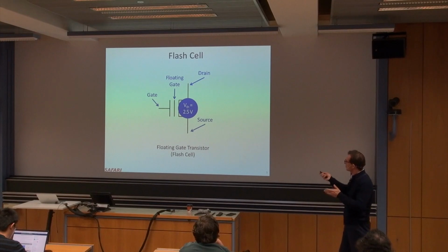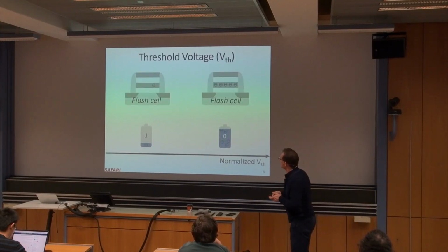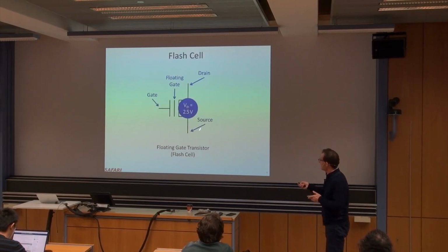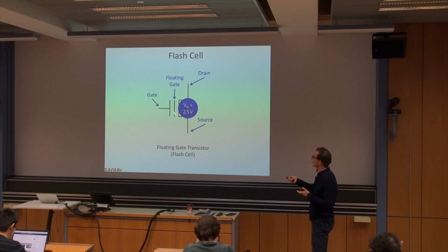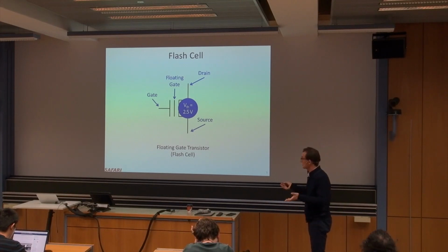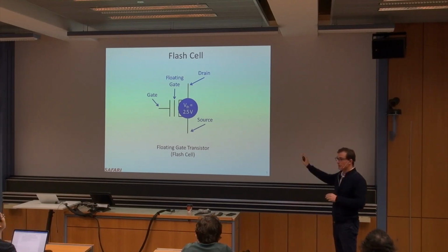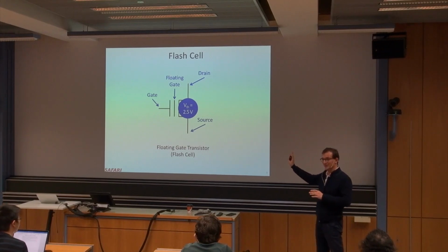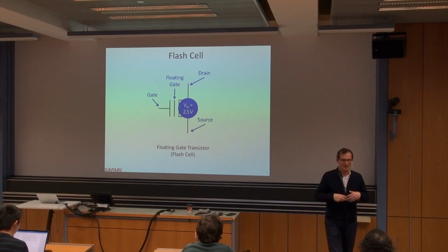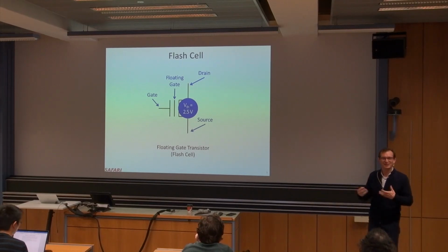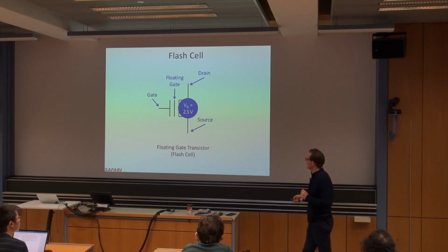So let's assume that the threshold voltage is 2.5 volts, right? And when you program threshold voltage, after you program it, you apply some other reference voltage, and the cell reacts in some way, depending on what voltage it's programmed to over here. So it can actually store the voltage forever. It's non-volatile, at least forever, meaning theoretically forever, of course, right? But in practice, you have a lot of other effects.